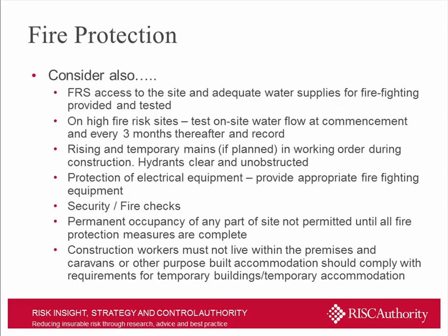The list goes on. Again, touching on the requirements for access for the fire and rescue services, and then on high fire risk sites, there are additional requirements for testing water flows to ensure that there's adequate water supplies should they be necessary. If you're installing rising and temporary mains within the building as part of firefighting shafts, then ensuring that they're fully functional at the earliest possible opportunity is going to offer a significant benefit.